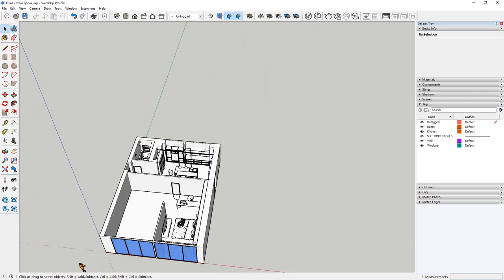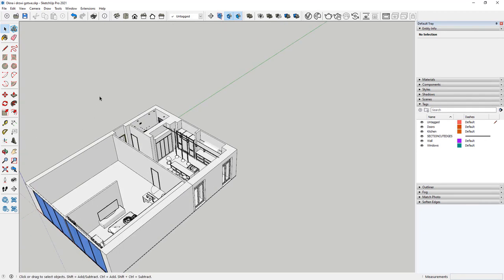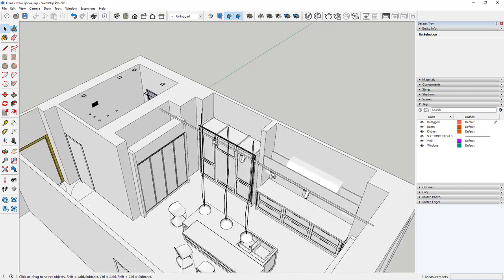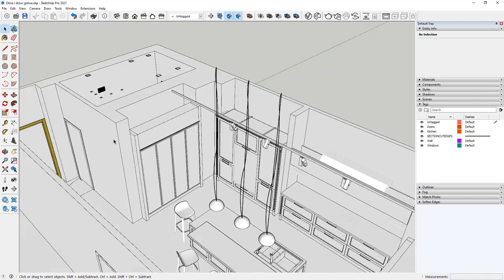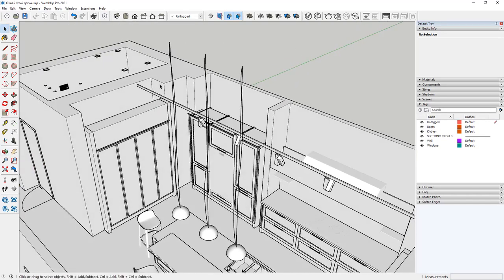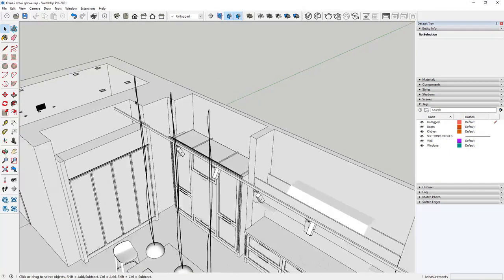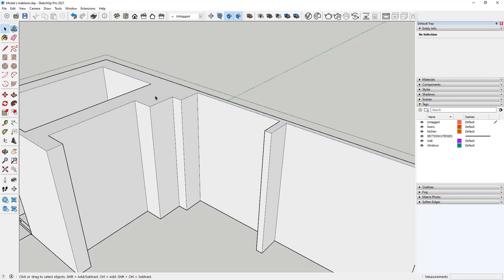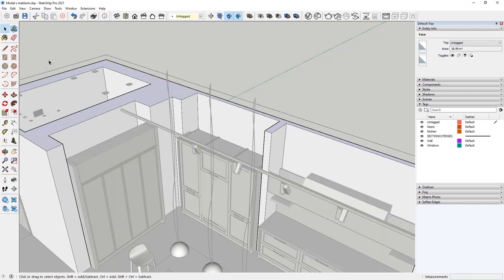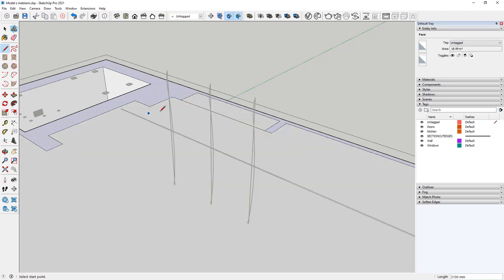Okay, the next thing that we need to add is the top wall or the wall elements that is placed above the furniture. So as you can see here, still we have some gaps, but now this will be easy to do. Just remember to switch into the tag wall and double click on your wall, and after that you need to create the elements. Of course, the easier will be if you will turn on the visibility for your furniture.